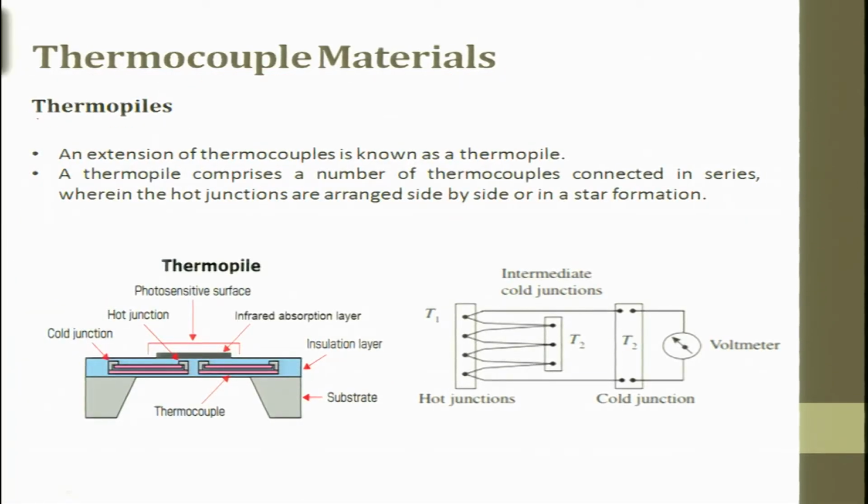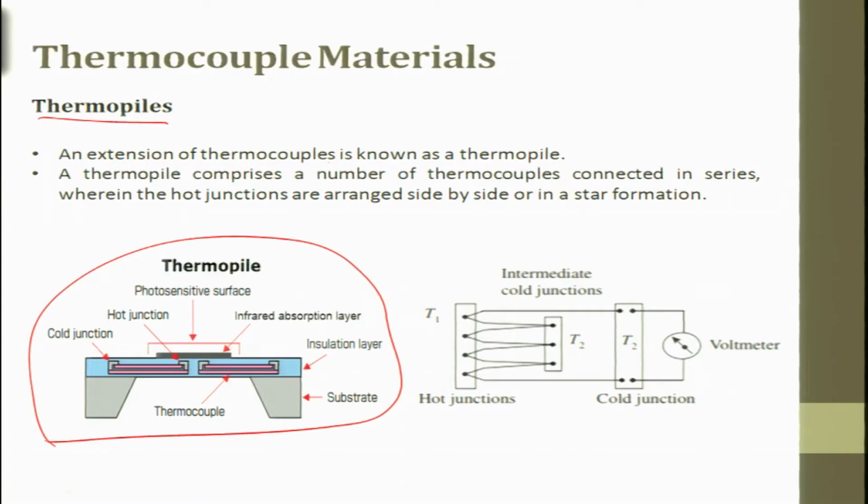Thermopiles, which are now getting a little bit popular. An extension of thermocouple is called a thermopile. A thermopile comprises a number of thermocouples connected in series wherein the hot junctions are arranged side by side or in star formation. So, this is a typical thermopile which is made from MEMS structure.